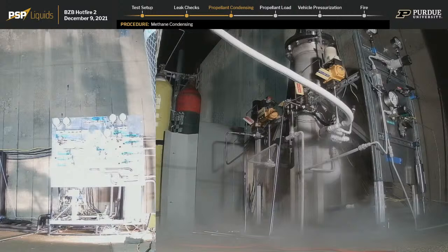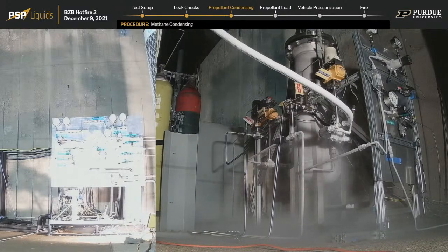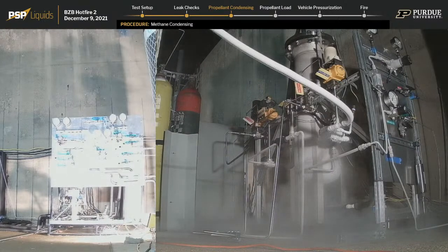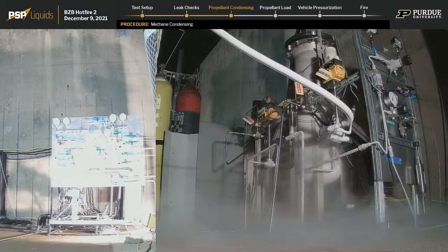Another great question in the chat, why is a needle valve being used for venting nitrogen instead of a pneumatic valve? So, the needle valve is being used in this case because it allows for very precise control of flow rate into the jacket, which is necessary because it is a very precise operating point that we need to keep the methane condensing at. Right. And I believe the abrupt changes you're hearing is actually a pneumatic valve that the operator has found is convenient to use, so that's why he uses it. But the needle valve provides us with a baseline, so we only have to do small adjustments with kind of a bang-bang-esque system, but just manual, of a pneumatic valve.